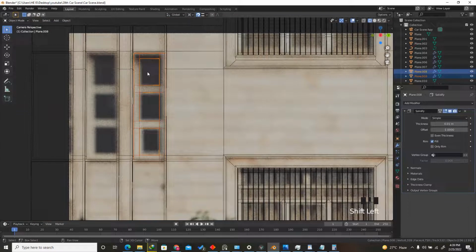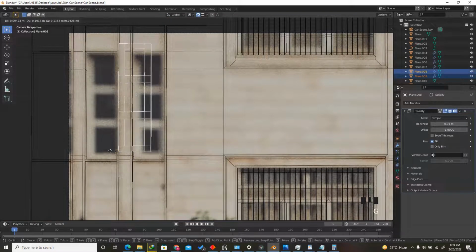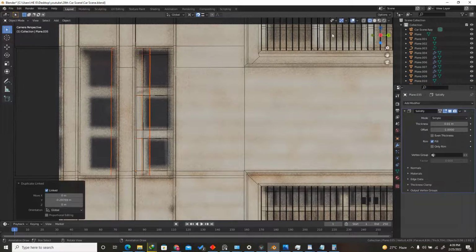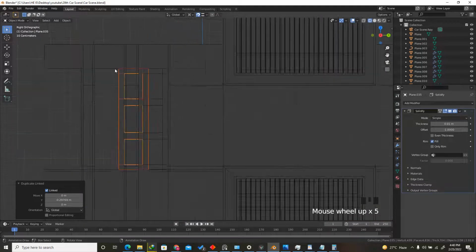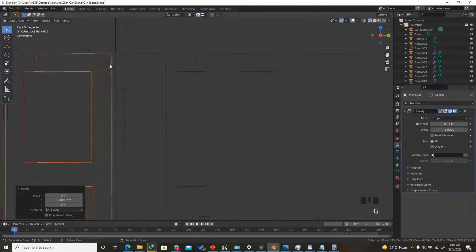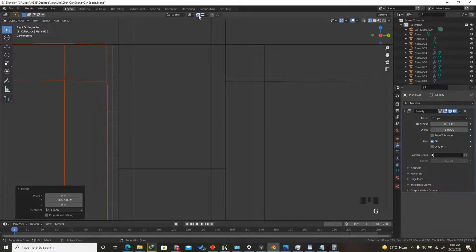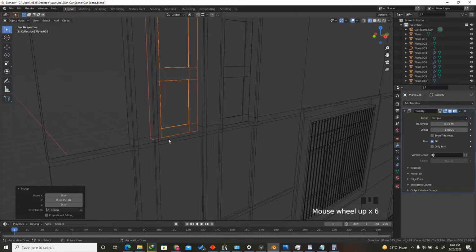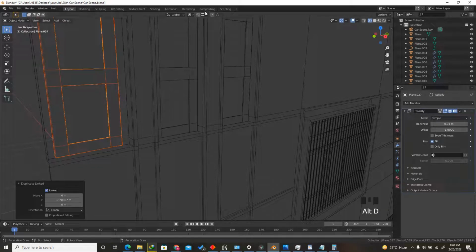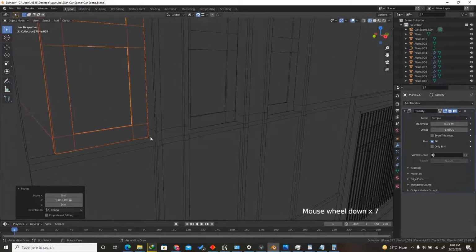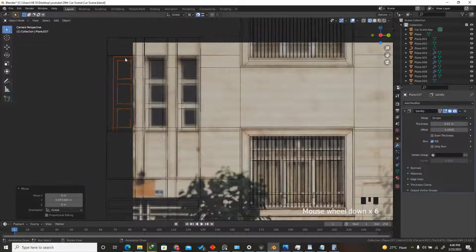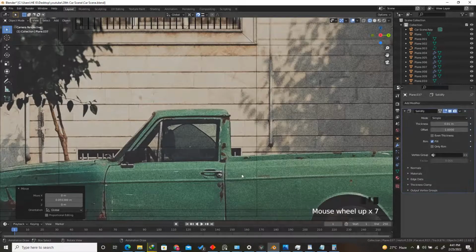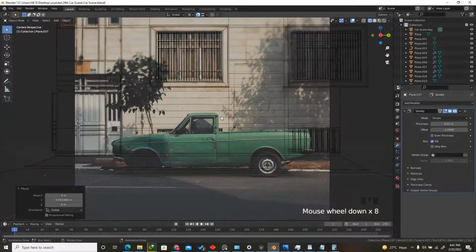I'm going to select this one and select the window later. I'm going to press G to see if everything is selected. Now everything is selected, and I'm going to press Alt D and then Y and move it on the Y axis. Let me go to this X view right here, and I'm going to press GY, and let me deactivate this snap button. Press GY and move it somewhere around here, and then again press Alt D and then Y and move it on the Y axis. Let me activate the snap button and then press GY and move it right here. So if I press 0, you can see we have successfully duplicated all of the things that should be duplicated. One thing I have forgotten is there's also an opening for the basement right here. So what I'm going to do is